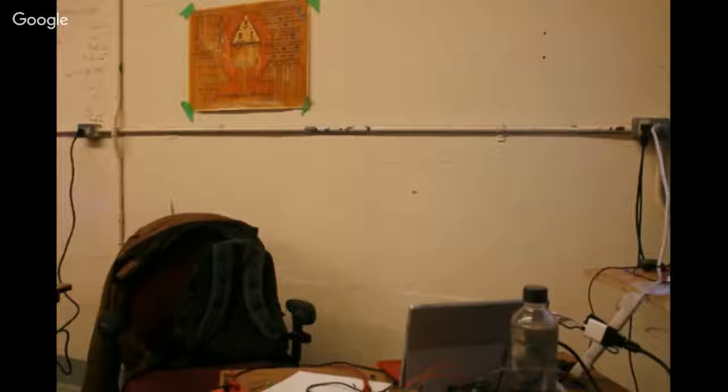When you were soldering, your beautiful job, very good, you did a much better job. There you go. Perfect. So you have a connection. It's happy with your blink program. So what I would do as a first step is just look through the code briefly, make sure you understand the setup, setting up pinMode for output, and the digitalWrite to turn it on and off with the delay loop in there. And that delay loop is what we were talking about with the timer function, that we didn't want to be a blocking delay like we have in here.